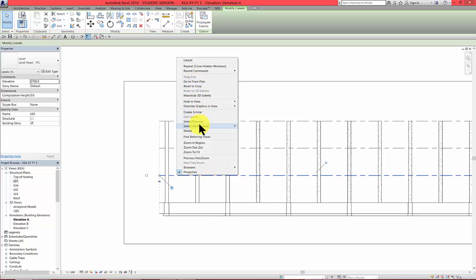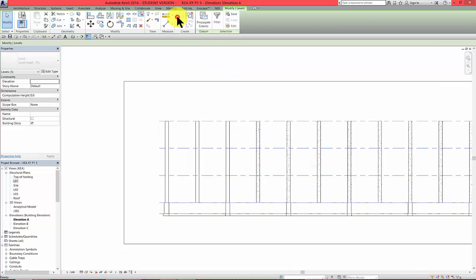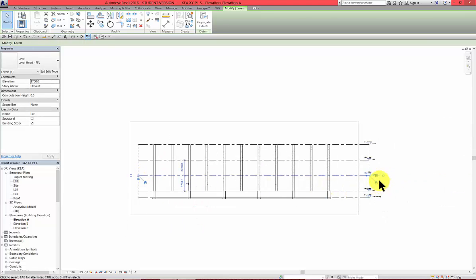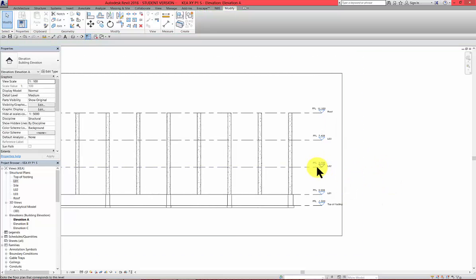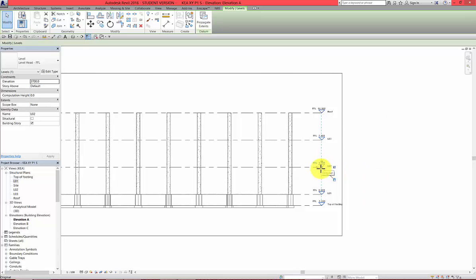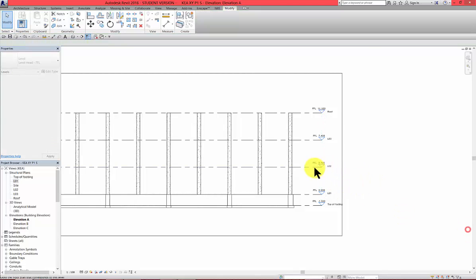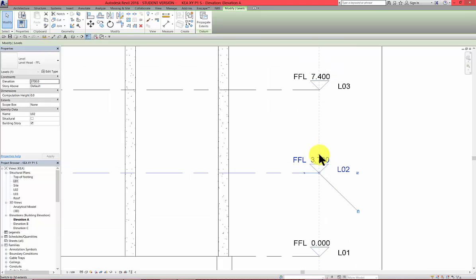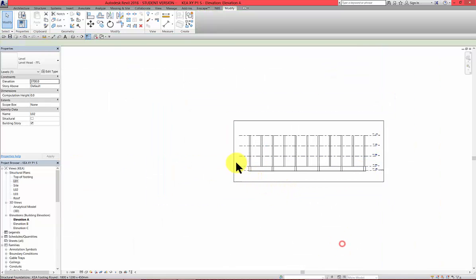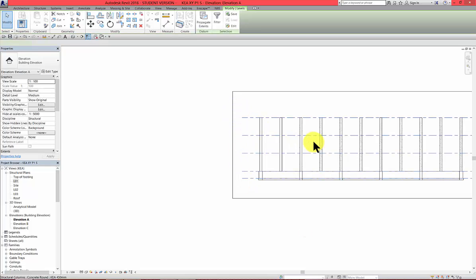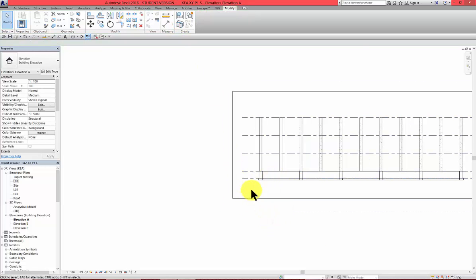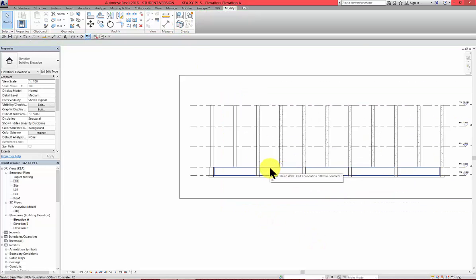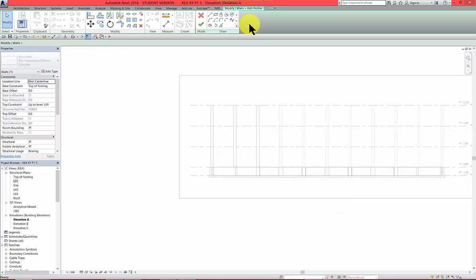So if I select all instances in the entire project, unpin it, then select one, stretch it, and then this can go back somewhere here, and this can go back to the rest. Make sure it says 3D. Yes, it says. Now, before I start to create steps, I would like to pin it, and then select the wall, edit profile,